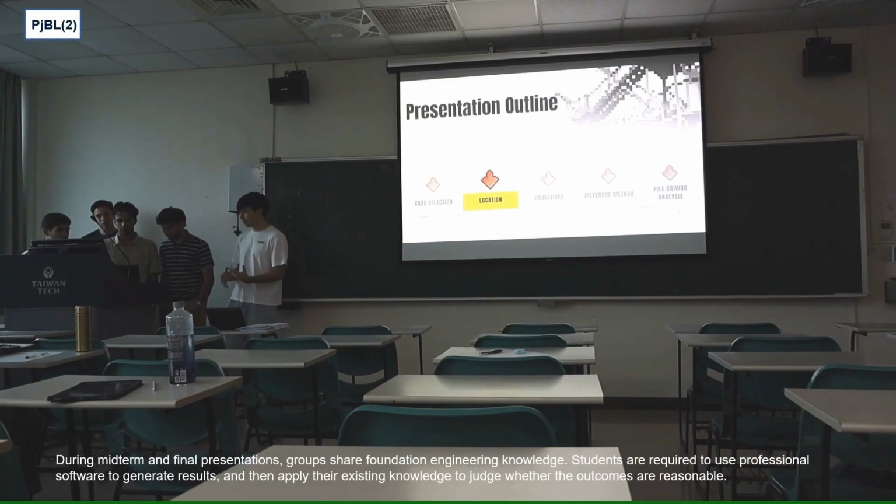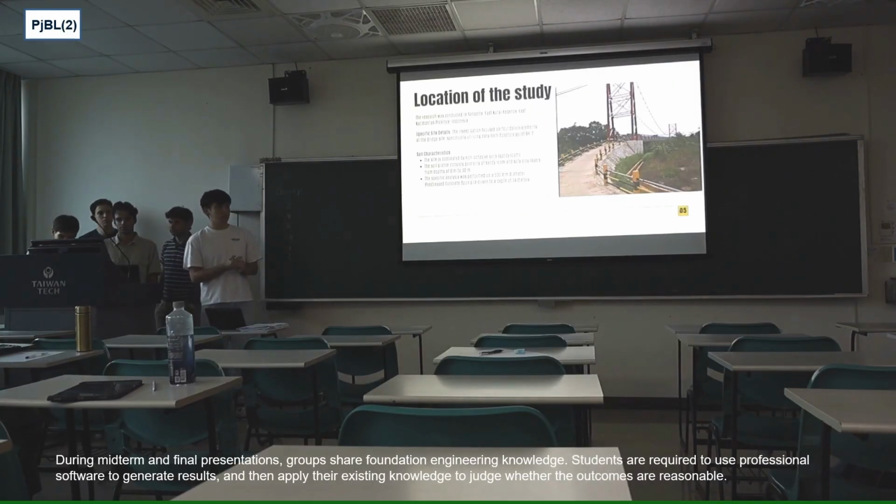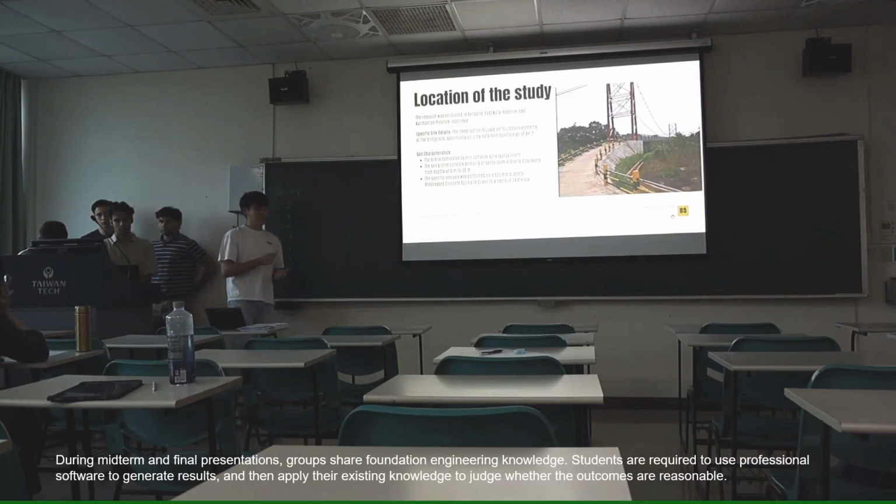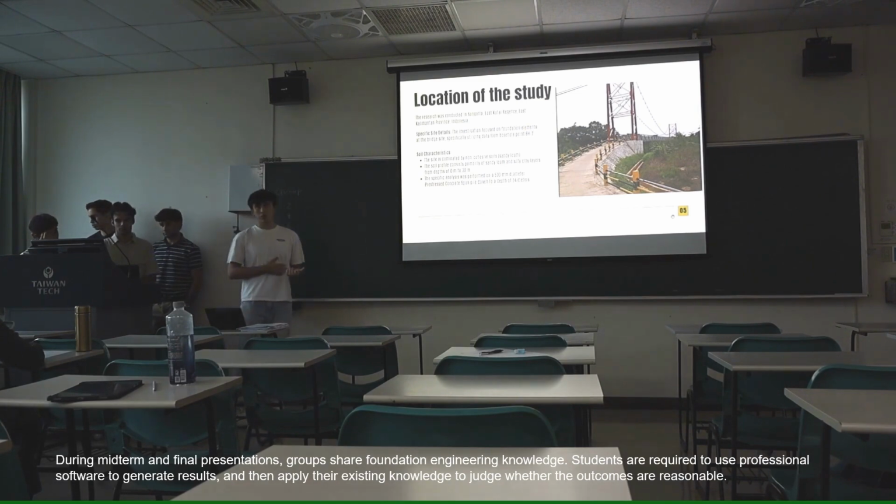This research was performed in Sangatta, which is located in the East Kutai Regency of Indonesia. Specifically, as my partner mentioned, at the Sangatta Lama Suspension Bridge construction site. In this construction site, the research was performed at borehole point DH2, where the soil profile around this point was non-cohesive soils, specifically with layers of sandy loam and silty clay. At this point the data was obtained to perform the research, and the concrete pre-stressed piles were tested.